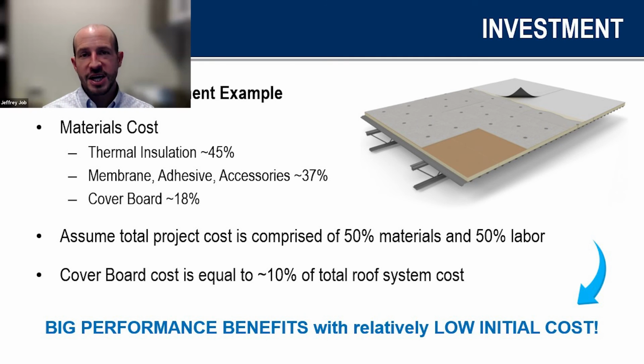I don't want to say critical, but what we consider best practice would be using a coverboard. Again, the gypsum ones tend to be very high performance, very competitively priced. And you can get some of the other trade-off benefits of less components, fasteners, securement based on the type of facer you're using there. So offset some of the cost of that coverboard as well.